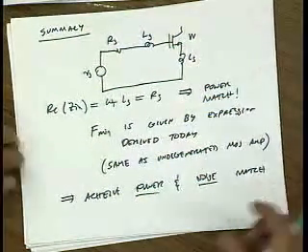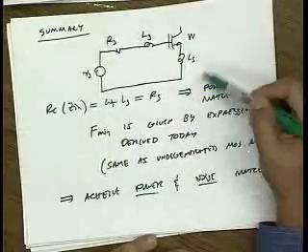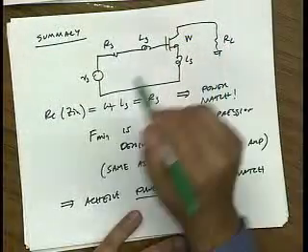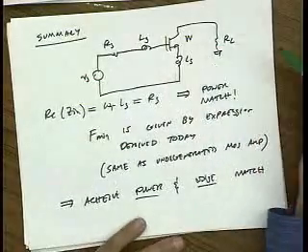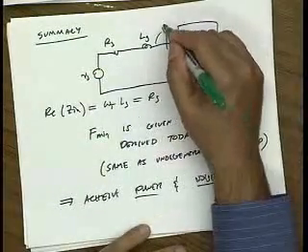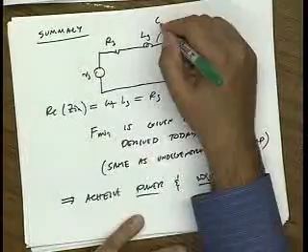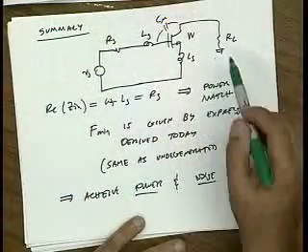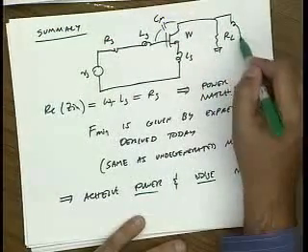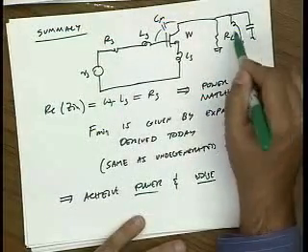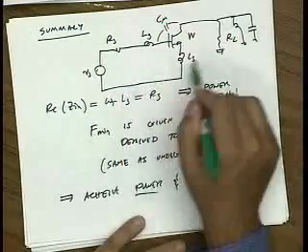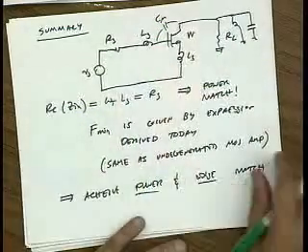Now, if you actually try to design one of these amplifiers, as I've shown here, let's say just driving a load, you'll find that it's actually quite a nightmare, because any real device has C-mu, right? And C-mu makes our device bilateral. If I try to use a tuning network at the output to tune out the capacitance here, any change in the output load makes a change in the input load, and it gets very, very ugly. So almost everybody uses a Cascode device.